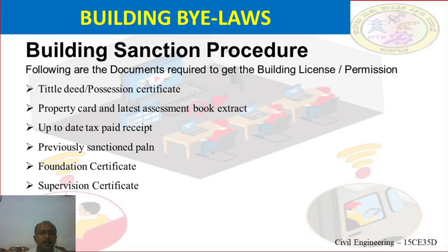This foundation certificate is based on the tests you conduct for knowing the safe bearing capacity of the soil, by conducting certain tests such as the plate load bearing test.